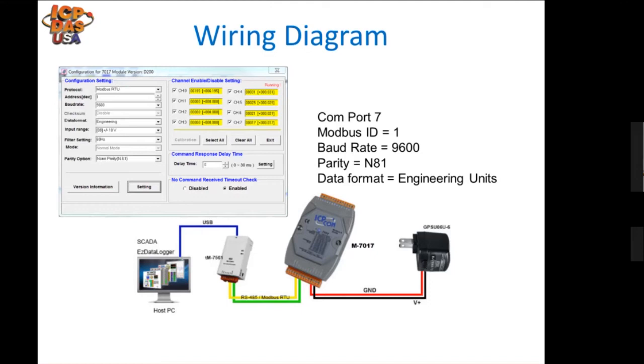Along with this, you want to connect your sensors to one of the 8 inputs labeled channel 0 through 7. And to complete the data logging steps, you configure the module using DCON utility. In the top left, I show an example of the configuration we'll be using.